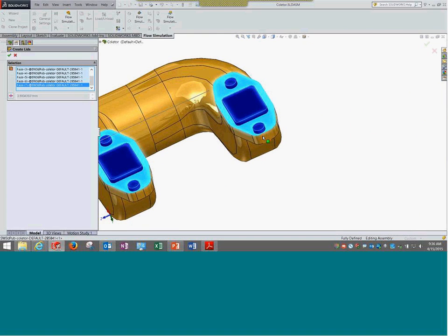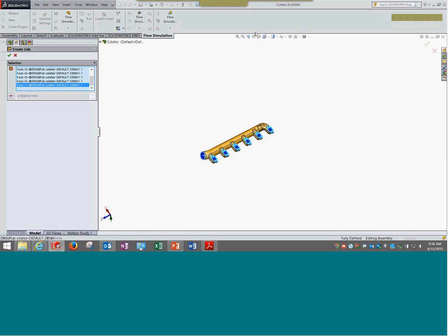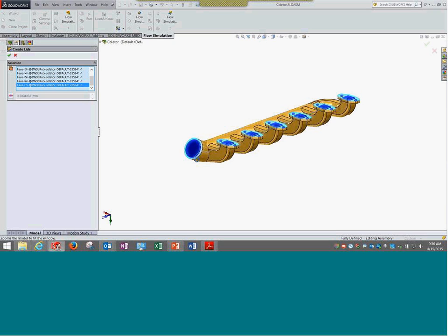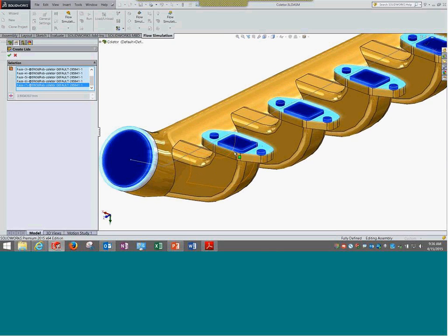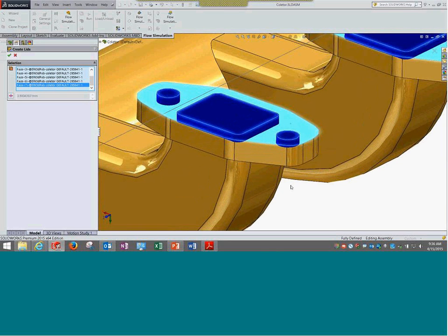Here, if we observe closely, these are nothing but extrude features of SolidWorks CAD which have been created. It will use the face as the mid surface and extrude the body on both sides based on its own judgment of the thickness of the geometry. However, if you want to change that value, you can go here and change it manually as well.